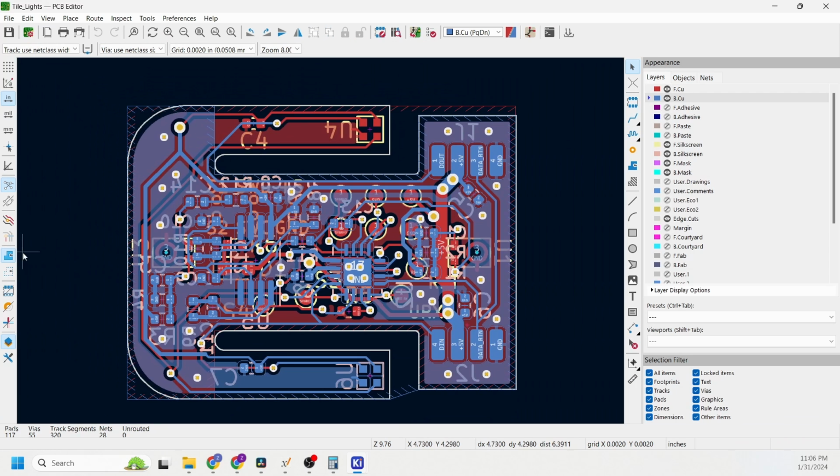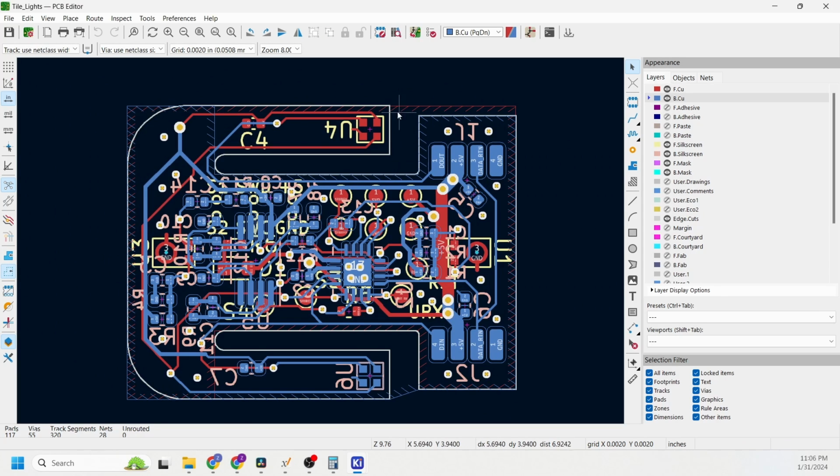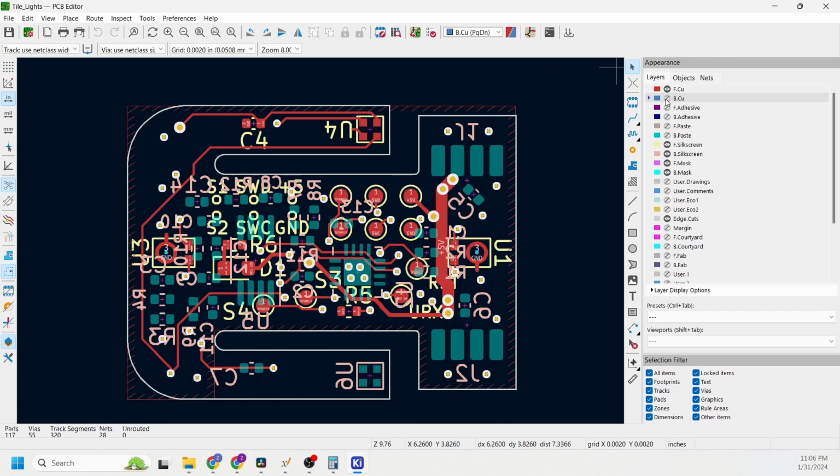Hopping over to the layout, we can see the unusual board design with the 2 arms. Each arm has LEDs on opposite sides. That way when I bend the arms to 90 degrees, the LEDs will point opposite directions, 1 into each tile. These boards are only 1 inch by 3/4 of an inch, making them 3/4 of a square inch, meaning they're going to cost me $2.50 each.